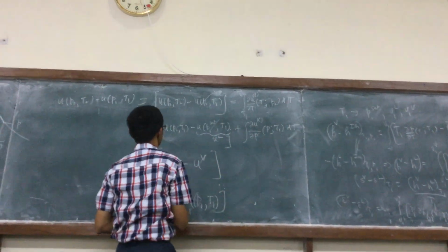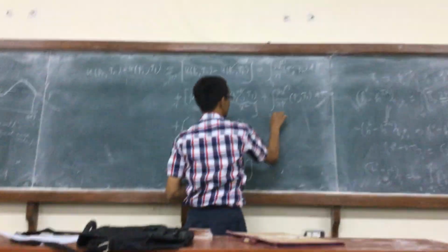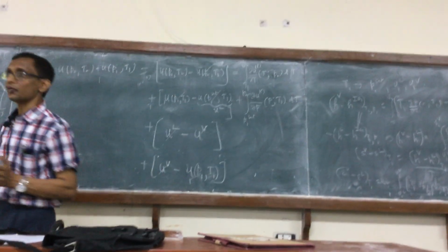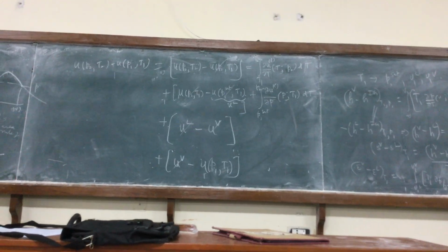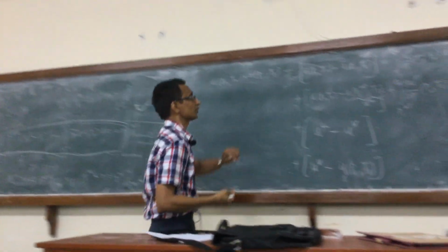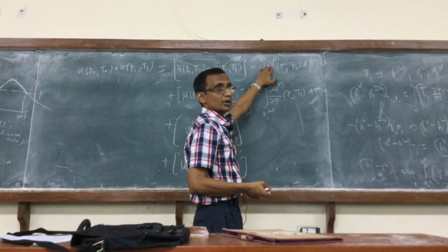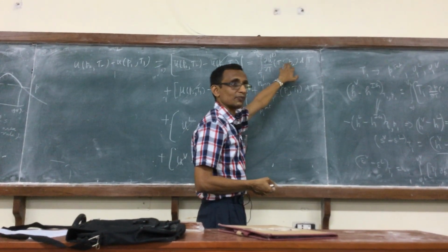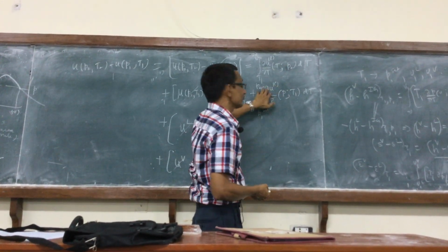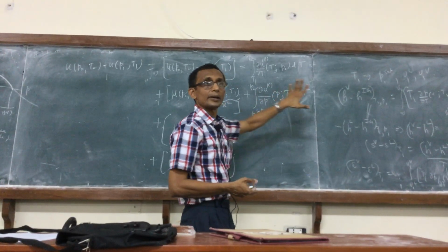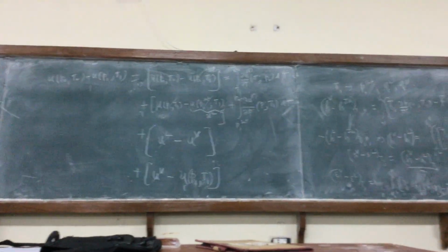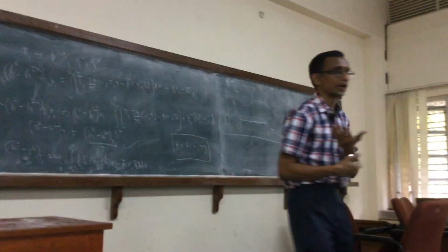Obviously the integral would be from P1 sat to P2. Now both of these are in the liquid phase, so the same equations that we used earlier would appear. So for instance, if this were H, this would involve the specific heat at that pressure, liquid specific heat at that pressure. This would be entirely dependent on the equation of state, but it is integration done in the liquid side of the isotherm.